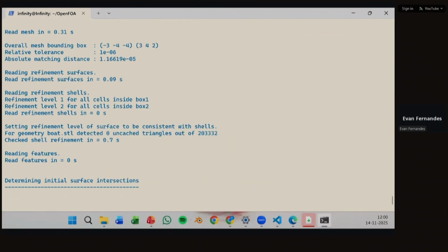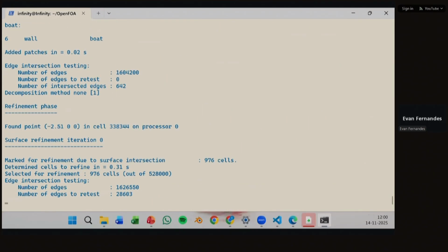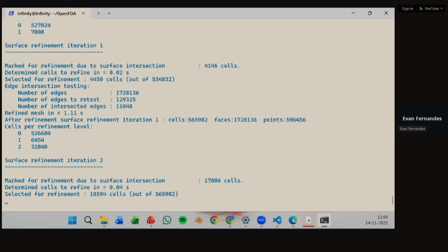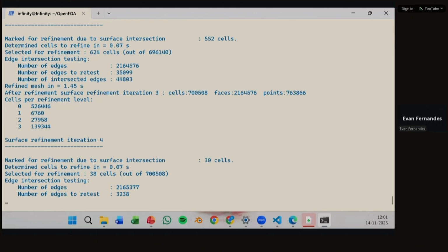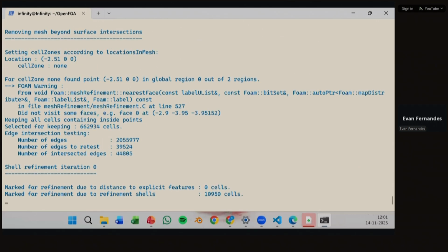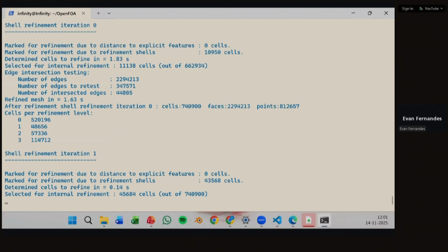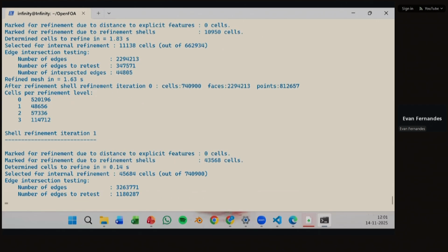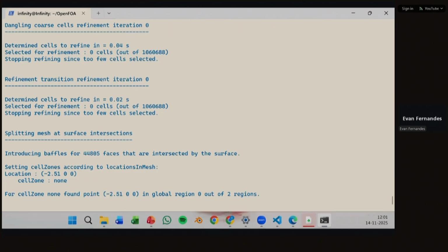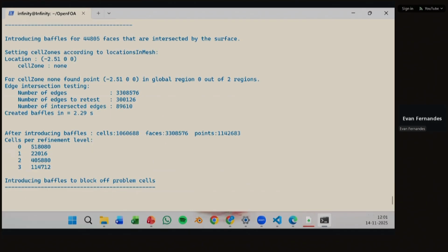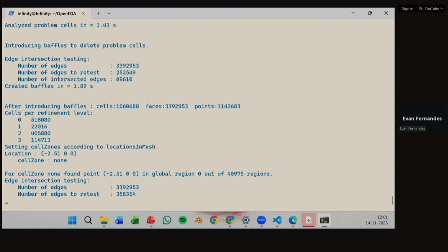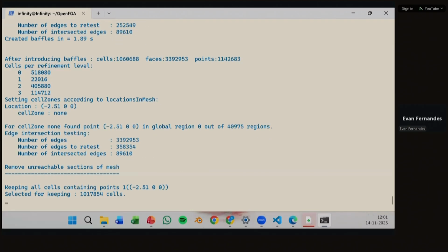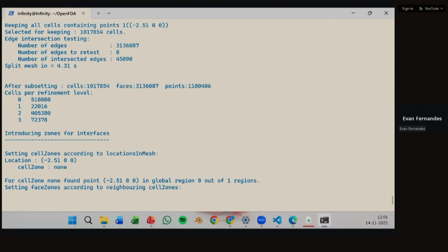Okay. So your override command is in simple terms just overwriting any previous data that it has, and it tries to interpolate the points that you have with your STL file and the block mesh itself. So it's just trying to merge your block mesh and your STL file together to create one uniform and unified mesh. So your snappy hex will take a little bit of time. Max it takes like around 1 minute. So let's wait for some time while this meshing is done.